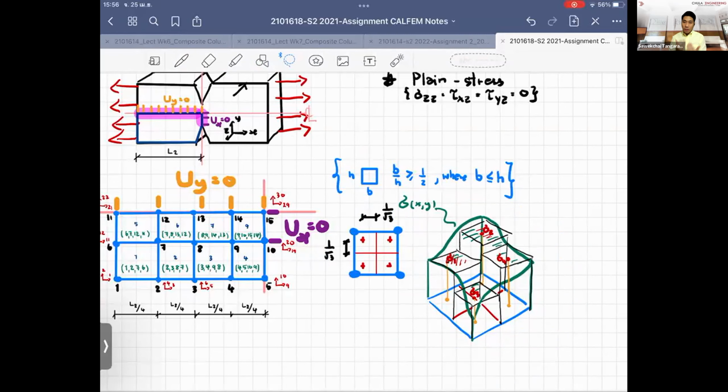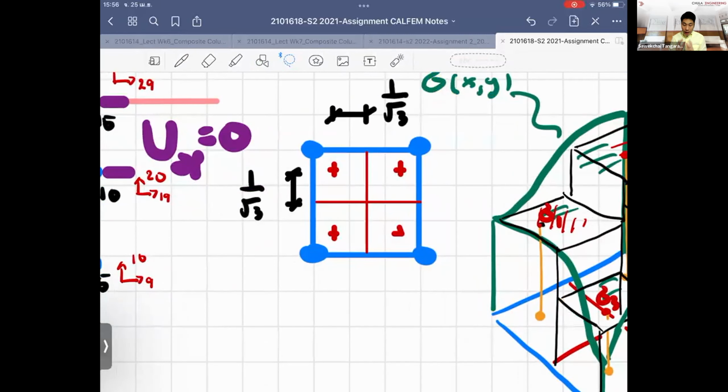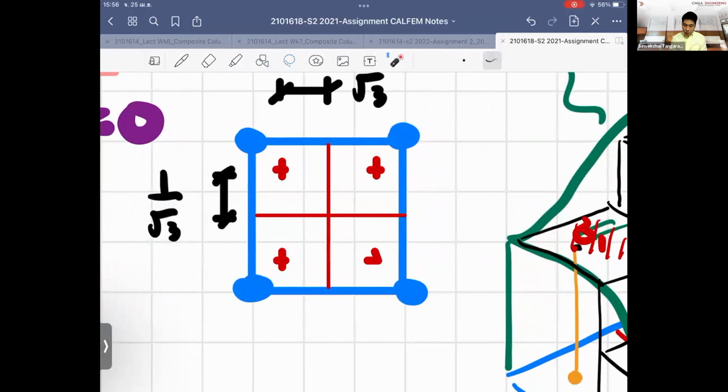That's why people make a couple of efforts, such as allocating more Gauss points inside the element domain. But having more Gauss points is not simply putting in more allocation. You have to increase the level of the nonlinear function you use.